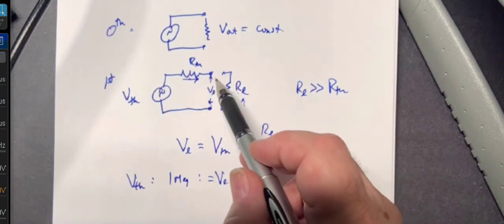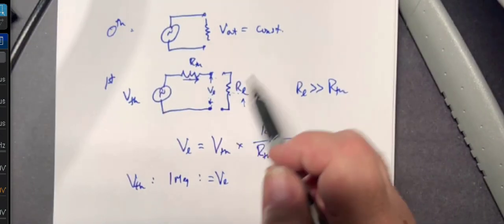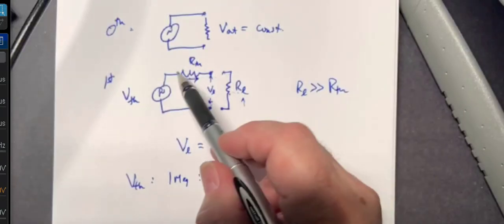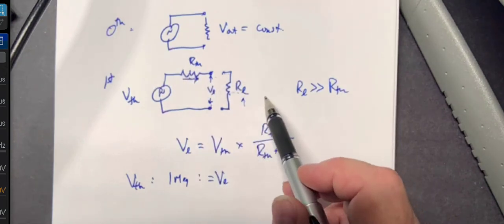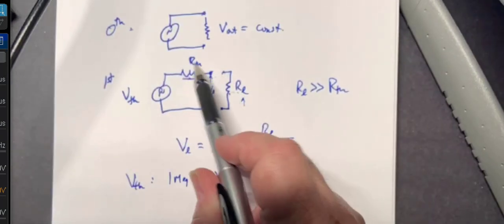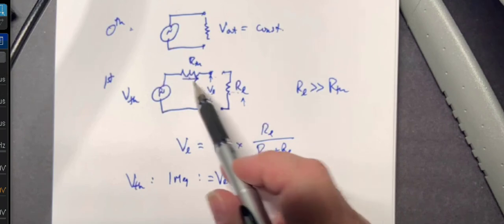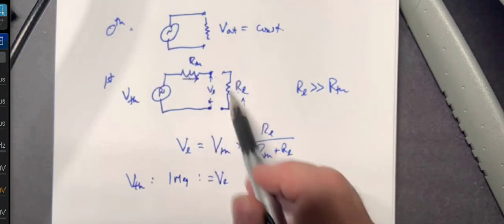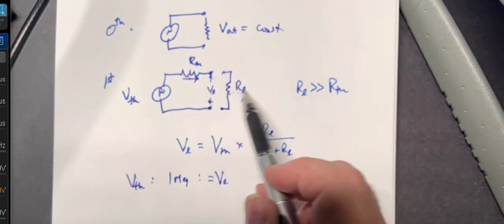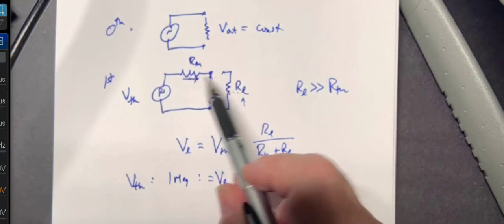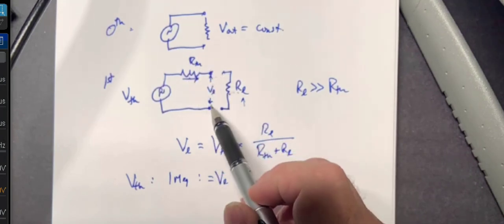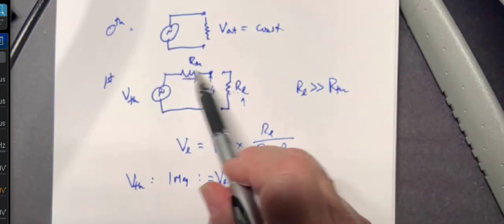Well, we have to apply a known resistive load, and we want to make one that's large enough so we have a reasonable voltage drop. And so something on the order of what we estimate or what we think the Thevenin resistance might be, if we can make the load resistance on that order or a little bit higher, then we'll be able to get a large voltage drop, and we'll be able to measure the Thevenin resistance.